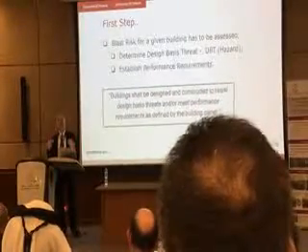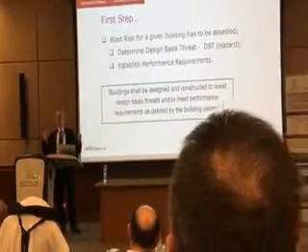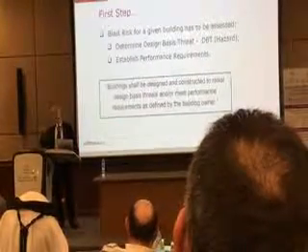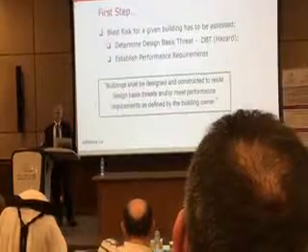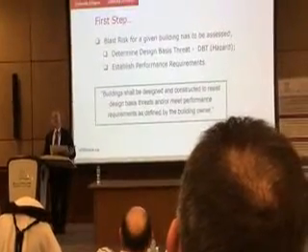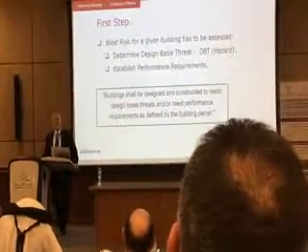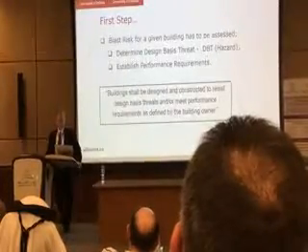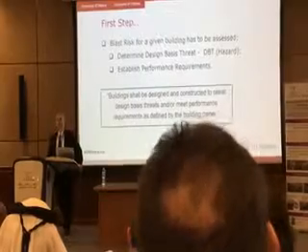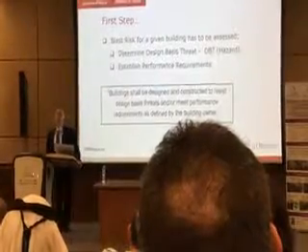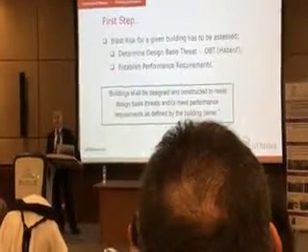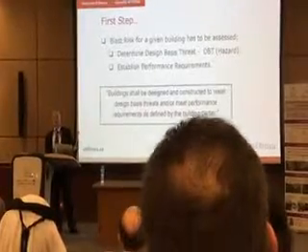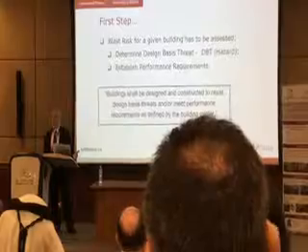So given that they gave me the charge weight and standoff distance, I immediately convert those to pressures and durations, okay? The next challenge is a professional structural engineering challenge, and that is deciding on performance requirements. Now we are using performance-based design. The building owner, in that case Global Affairs Canada, has to decide how important that building is.